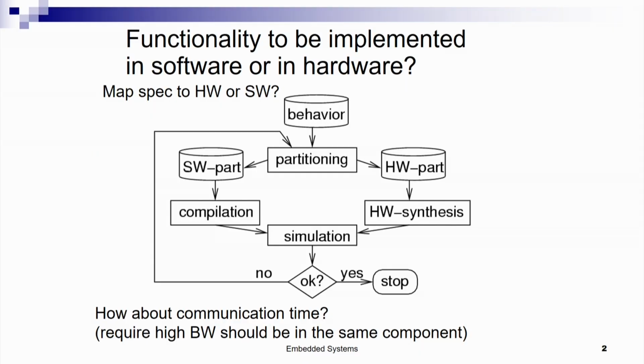Once modeling is done, the next step that we embark on in embedded systems design is hardware software partitioning. Firstly, we are given the designed behavior, that means we have the models in terms of, say, concurrent and hierarchical FSMs, HCFSMs, and then some nodes of that HCFSM will be designed in software and some in hardware. By software we mean that we will have a C code.